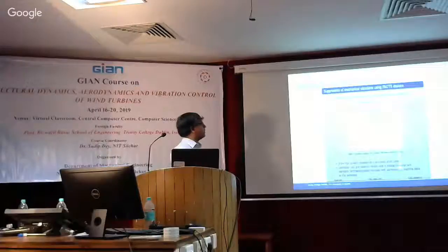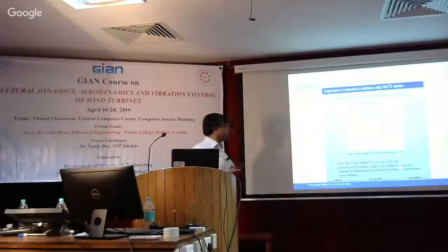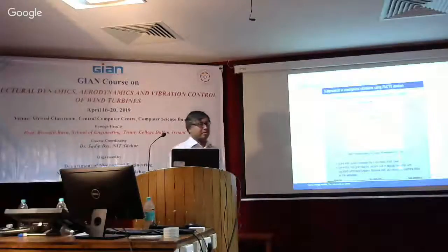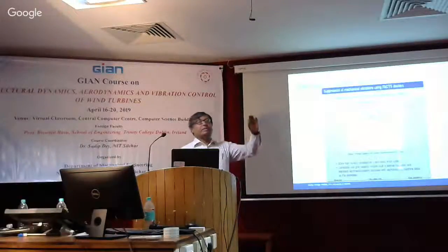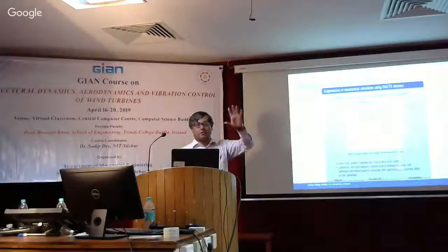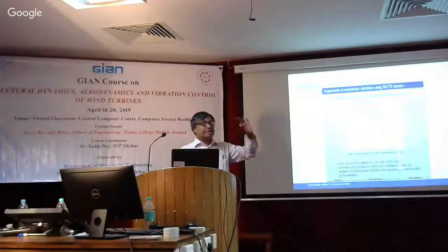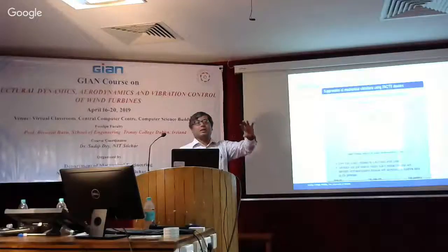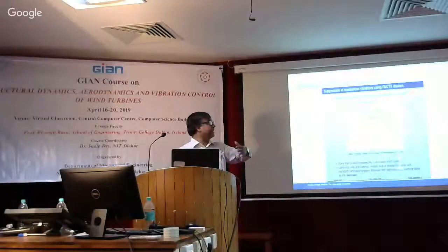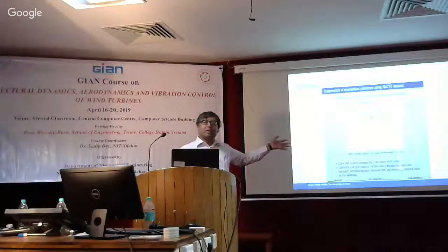This is actually the suppression of wind turbine vibrations due to electrical faults and grid faults. As you know, there are sometimes faults in the grid system. By fault I mean, for example, a dip in voltage, where the power suddenly goes off, or there's a change in the frequency of the power, 50 hertz or something else. All this has an impact, and it actually translates to a mechanical vibration problem, essentially.